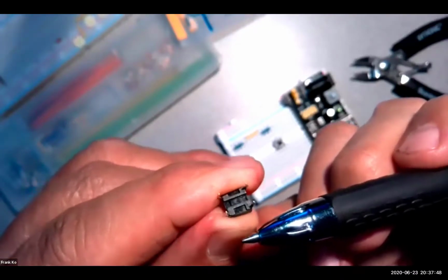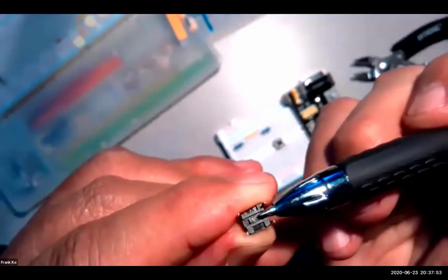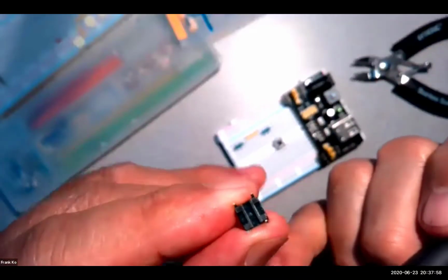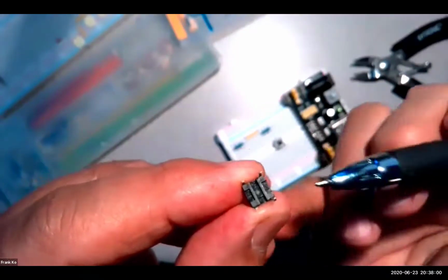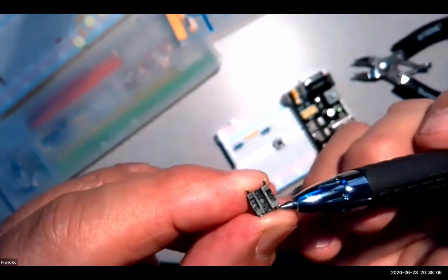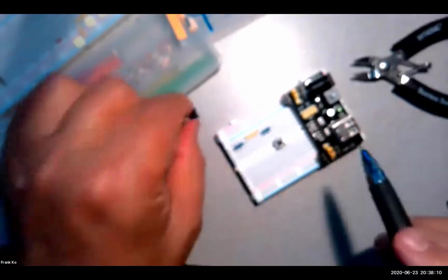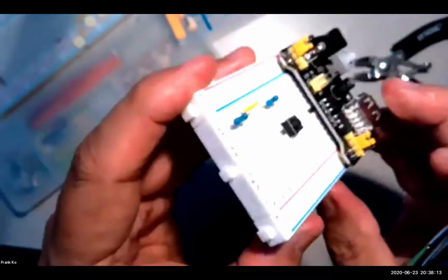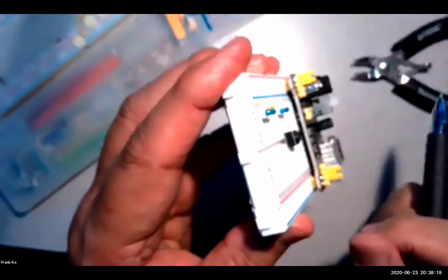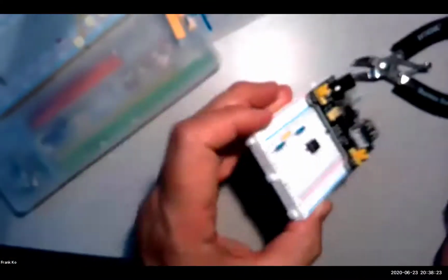Don't turn it 90 degrees and force it this way. If you try to straddle the groove this way, you'll end up breaking the switch. Rotate it so that you have this orientation, and the pins that are closer together will go on one side of the dip support groove. The other pins that are closer together, as shown here, will go on the other side of the dip support groove, and it ends up on your board like this. Okay, and yes, you do give it a nice firm push down, and it will go onto your circuit board just fine. Now, LED.